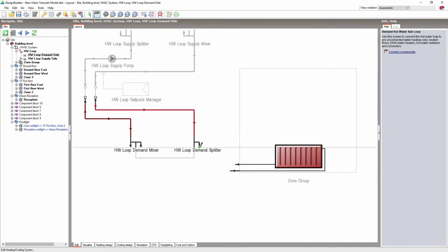After selecting a node, I move the mouse in the required direction to enable me to draw horizontal and vertical lines. Drawing guides help me to quickly locate existing endpoints, so I can simply left-click to define a change of direction, then left-click again on the radiator snap point to connect that pipe.